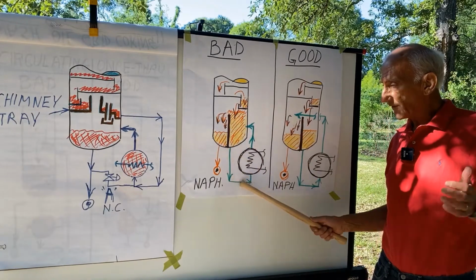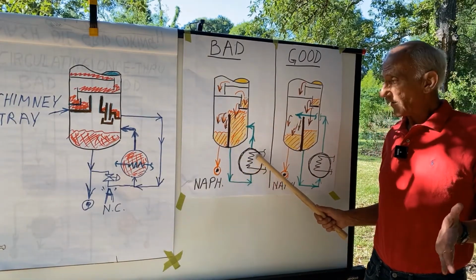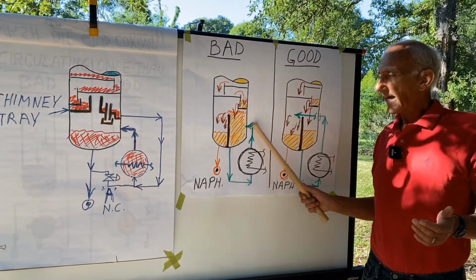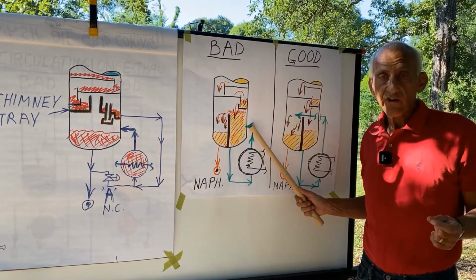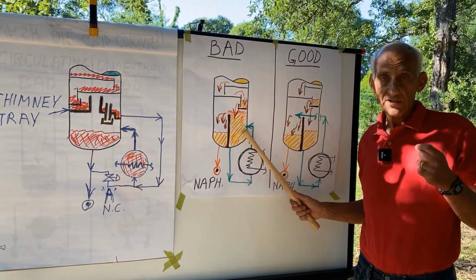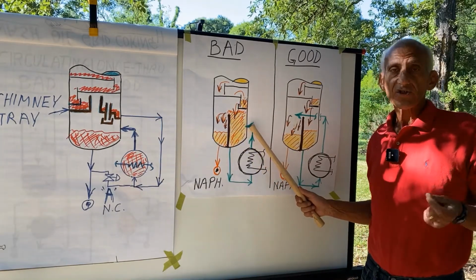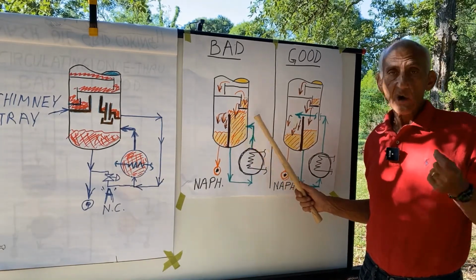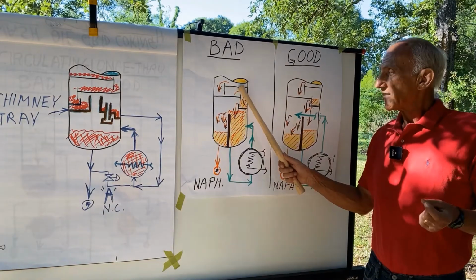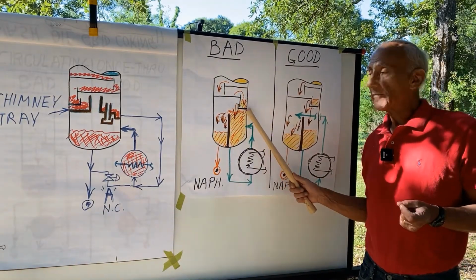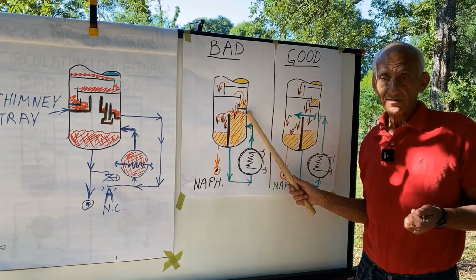Fine, the liquid now flows as it should into the reboiler, and it now returns as per the industry standard, but not my standard, back onto the cold side, where it commingles with the liquid overflowing from the bottom fractionation stage.